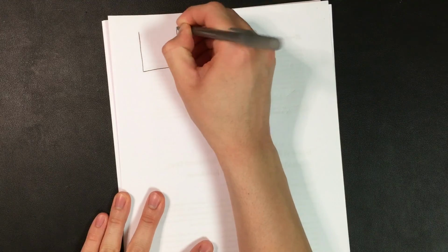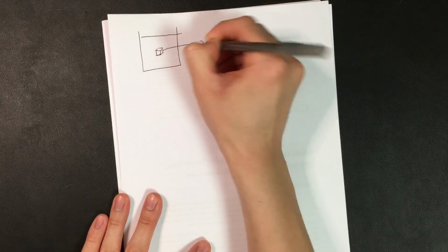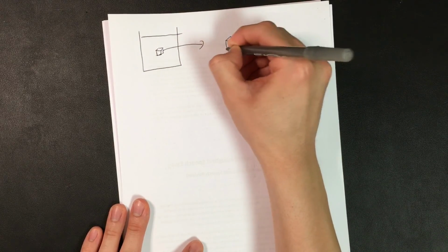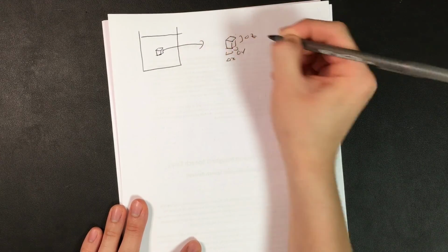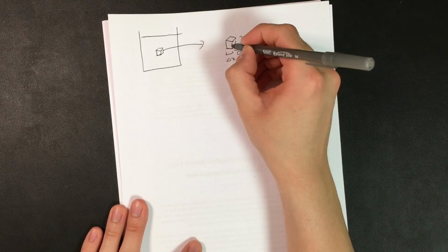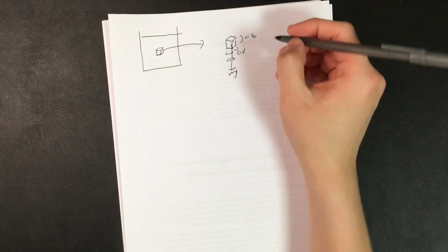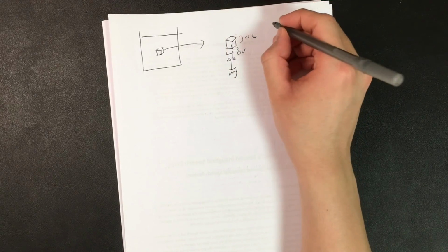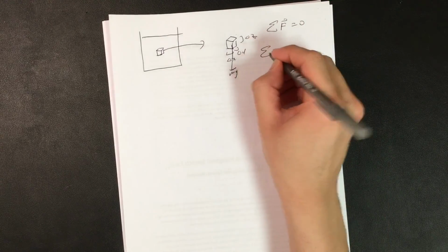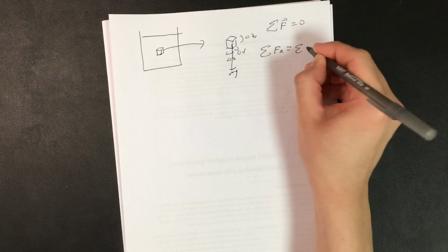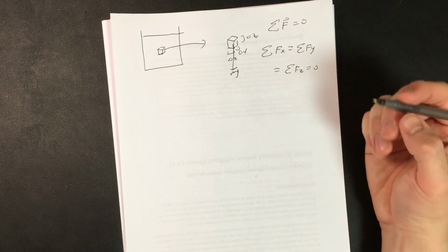So let's say there is water in this cup, and I take an infinitesimal mass such that the dimensions of this mass are delta x, delta y, and delta z. Drawing the force diagram, there is the weight mg that is exerted along the z direction. But since this fluid is under static equilibrium, the sum of all the forces must add up to 0. Therefore, the sum of the forces in the x direction, the y direction, and the z direction must each add up to 0.